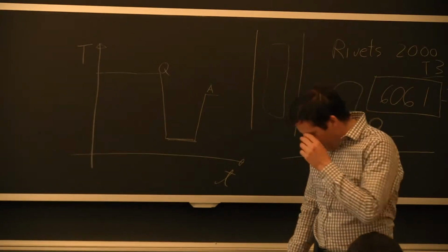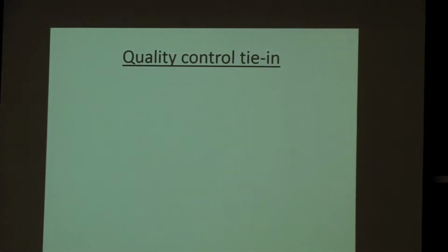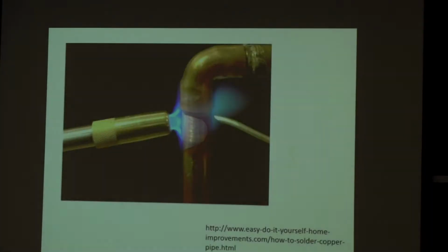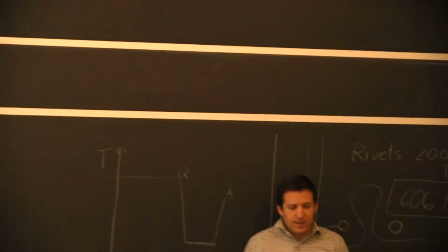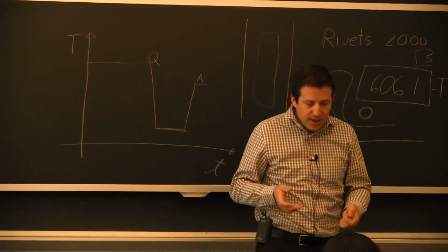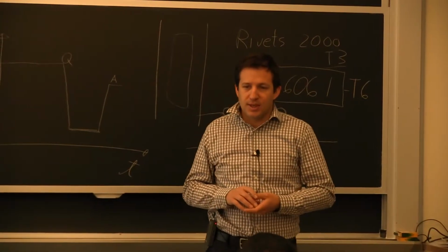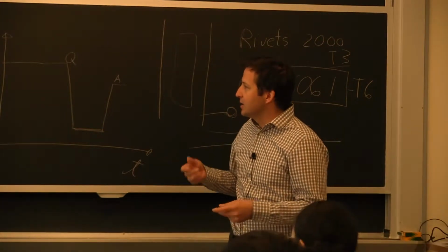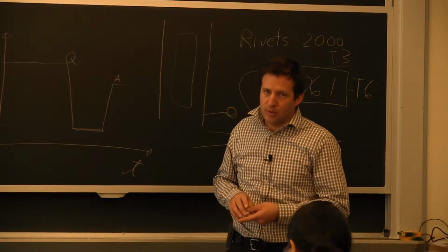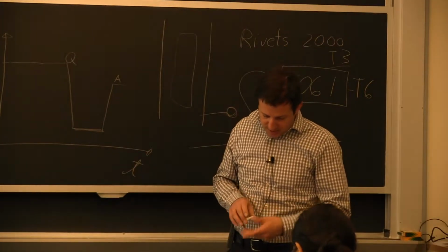So last time, in my third lecture on the use of materials, I talked about quality control, and one aspect that came in was workmanship. When we had the solder joint, I passed it around and essentially said, whether you get a good coverage, a good penetration of the solder in the socket really depends if you're going to do a good sanding job and if you're going to apply the flux and heat it properly. And it's experience, but every single time there's some variation in how you manage to do this soldering process. And it's the same in welding.